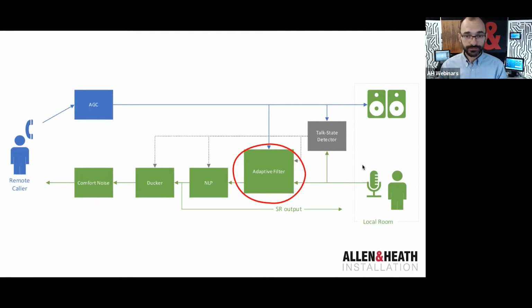So luckily, there are techniques for reducing that computational requirement, and the best known one is to apply the filter in the frequency domain instead. The trade-off, the compromise with that solution, is that any transform of useful length in the frequency domain automatically incurs latency, so you will have some extra latency.